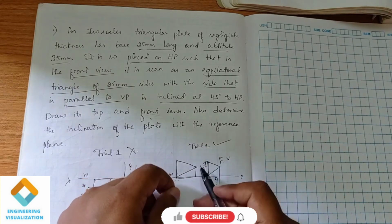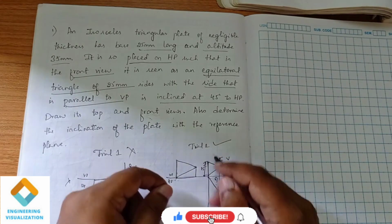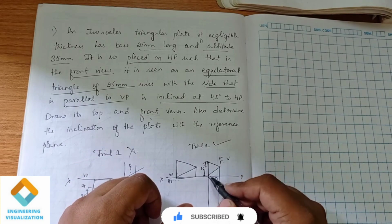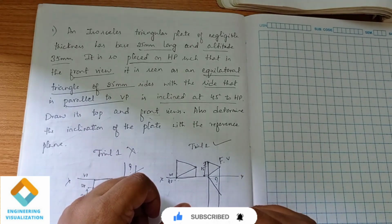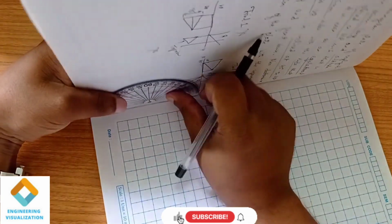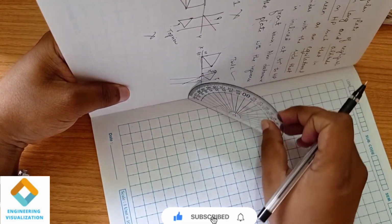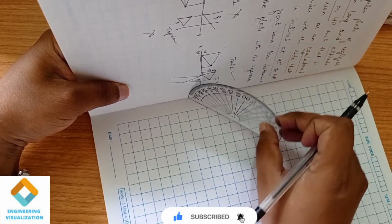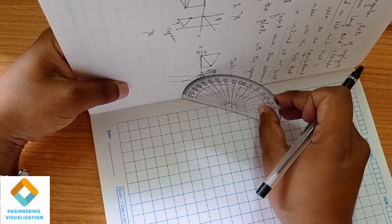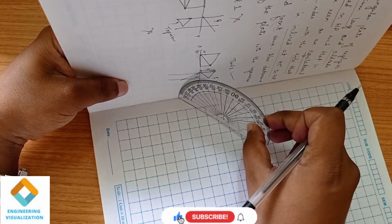So when it is inclined in the second position, it is seen as an equilateral triangle of dimension 25. Say consider this is our isosceles triangle placed like this, and in the second position we are inclining it. We don't know how much inclination, but in the front view we are getting an equilateral triangle, so that angle we are going to find out.